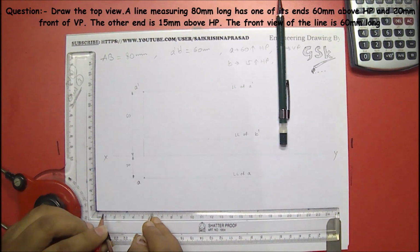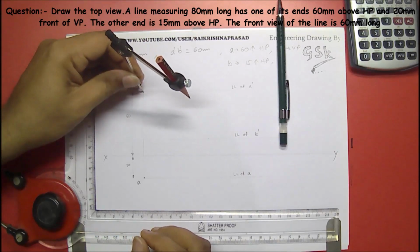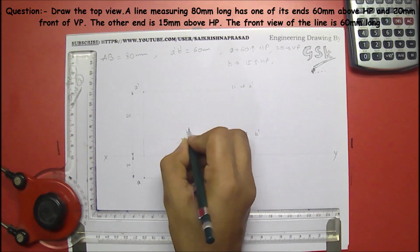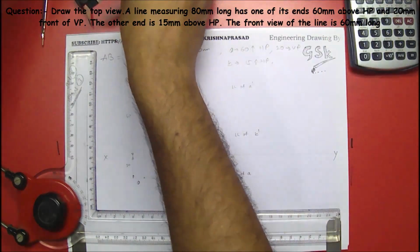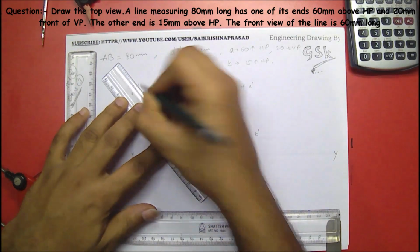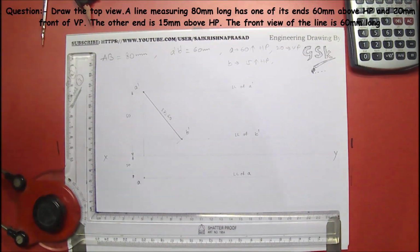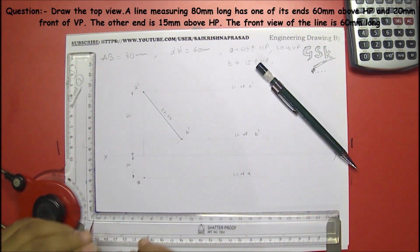So let me measure the 60 and, keeping on A dash, just draw an arc which cuts this one. This would be B dash, and this line is the front view. This is the front view, 60 mm, right? Now the true length is given as 80 mm, so measure it 80 mm.